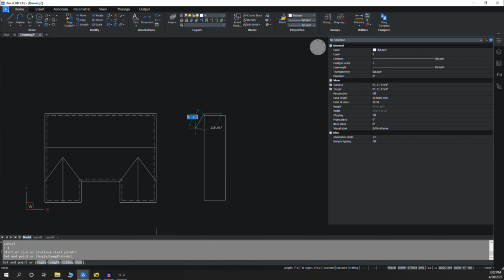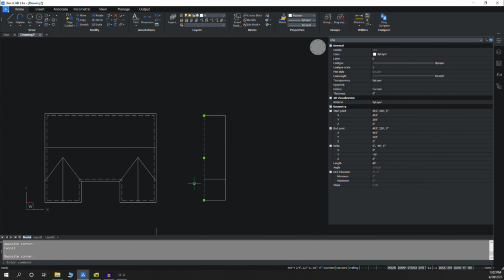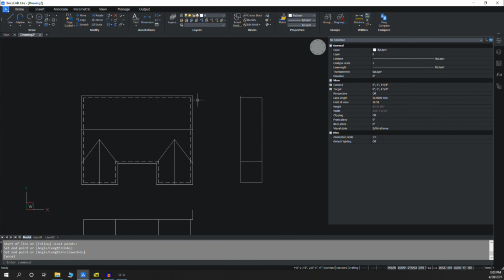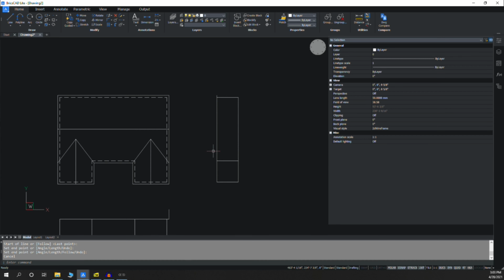So we have a 12-inch eave. And then let's pick up this interior wall here. Even though this won't show up on the side elevation, it'll be helpful for us when we're building our roof. I want to break that line into two, so I have a midpoint I can actually use. Now remember, this part of the roof is a 6/12, so we've got to make up a 6/12 really quick. I'm going to go down 12 feet, and up 6 foot. And then I've got that roof slope that I can just move into position right to the edge of the eave there.